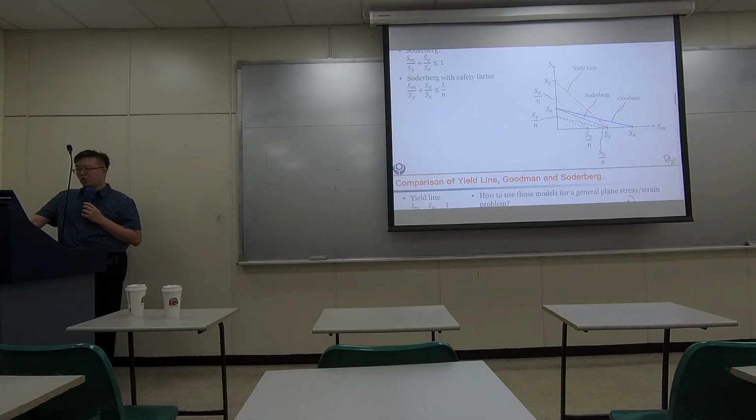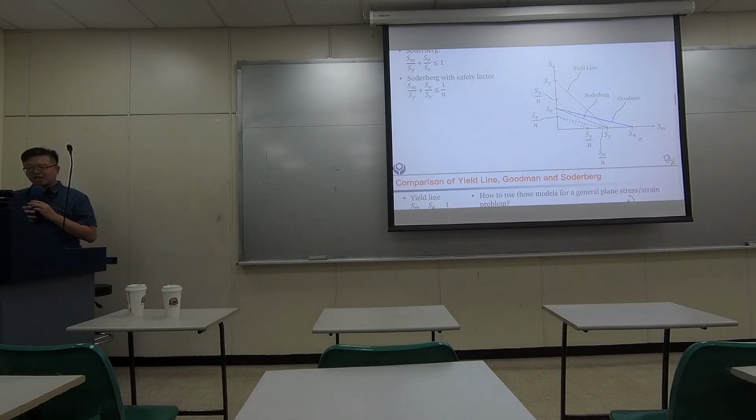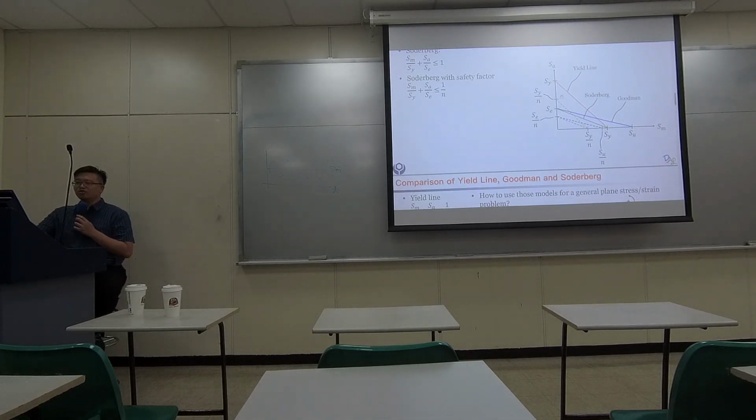Okay. So for the horizontal axis, you have upper limit at the yielding point and the ultimate tensile strength. For the vertical one, there's the endurance limit and the yielding strength. So usually for metal, ultimate tensile strength is greater than the yielding point, and yielding point usually is greater than the endurance limit. Endurance limit could be as low as a half of the ultimate tensile strength. Okay, so usually the yielding strength and the ultimate tensile strength are not too far away.